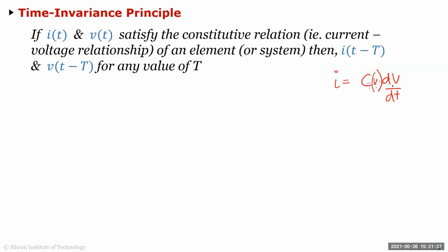So when you said it is C dV by dt, you actually answered it incorrectly. It is probably a function of V. So the capacitance is changing as a function of V, just like the diode, right? So it is like C as a function of V, same thing, dV over dt.